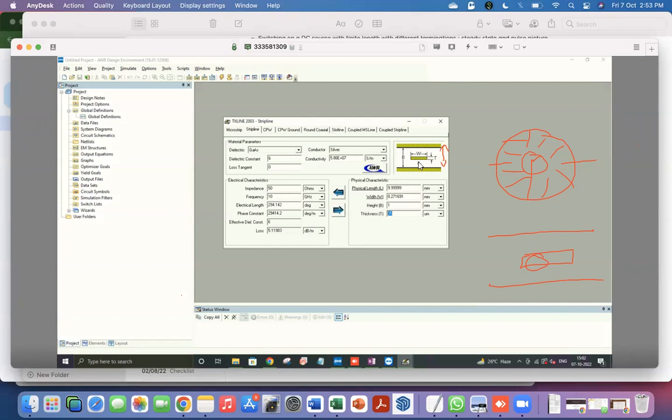And this is one of the devices we'll be studying in detail later on, but it's a 4-port device. So it's basically just two transmission lines close to each other. Each transmission line has 2 ports, and you are able to achieve a certain kind of property which you want from that particular device. Okay, so that's the strip line.